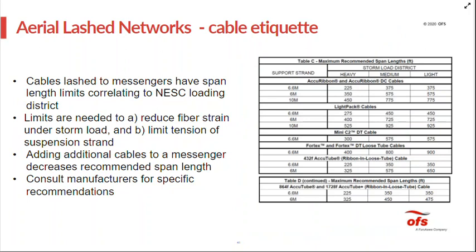And there's one additional thing to highlight is that as you add additional cables to a messenger, that is going to increase the weight. It's also going to increase the overall bundle of cables when you put ice on them, and that's also going to increase the amount of strain that whole system sees in wintertime.